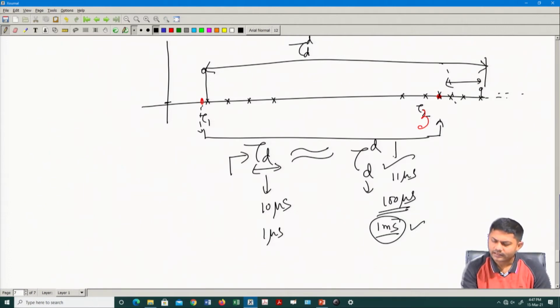I will not consider, from now, it depends where exactly you can think of your delay spread. Now, as you notice in the practical sense, when you have a digital modem, this is difficult to find. The reason is that you observe a system only by sampling. You do not do any processing at the analog or RF side. Had I done analog processing, where I can precisely see where my taps are, it is easy to find out, but I do everything on the digital side.